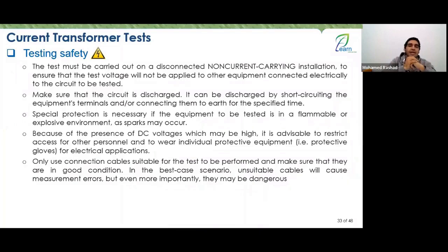He didn't realize I was behind the circuit breaker, so I got an electric shock, but there was no problem because the device has a current limiter. So as soon as it exceeded a certain limit, around 10 milliamps or 8 milliamps, it cut off. I mean, that's quite strong, but we should be careful and take care of ourselves. And we shouldn't touch anything while conducting a test or let anyone enter the zone of my test zone.